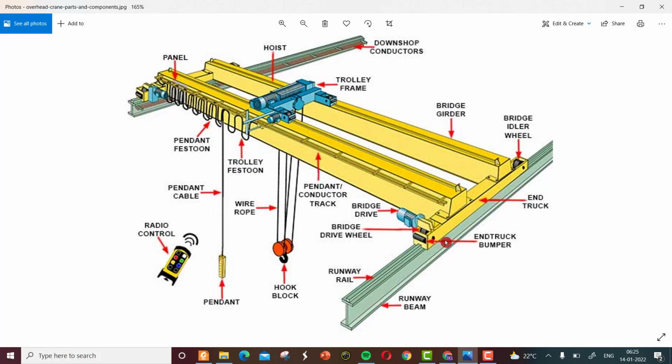The last beams you can see at both the edges are called the gantry girders, and these gantry girders will be supported on the columns. There will be numerous columns in a room, and in between two columns the gantry girder is continuous, and a span is taken between two columns. So we are supposed to design this gantry girder for this arrangement.